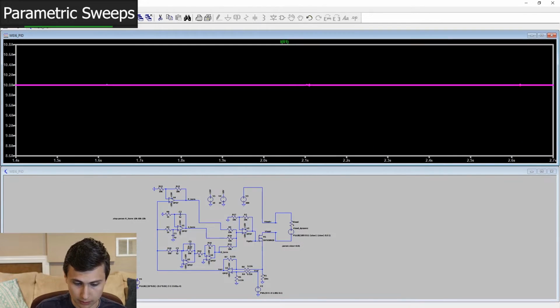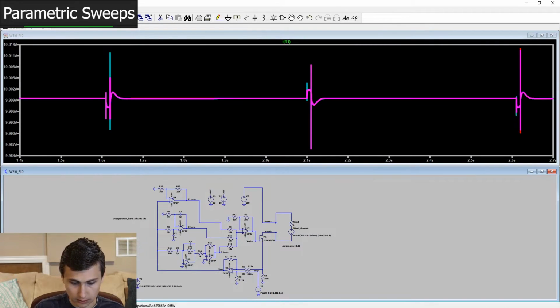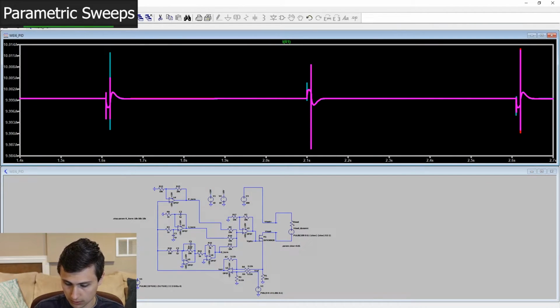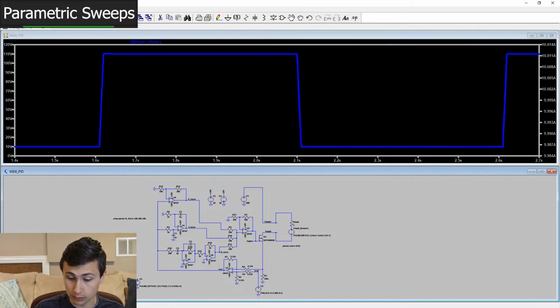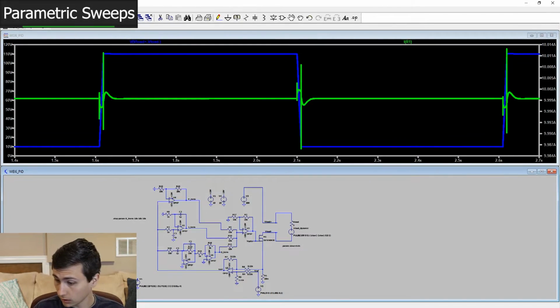And we notice there are some little hiccups in the current when the load has one of those transient events. However, the current is quite constant. It never really gets much further away. I mean, it goes from 10 to 10.011. So even in a very drastic, that's like a 100 volt transient on the output. So that would be, if our controller did nothing, the difference in current through that 1 ohm resistor would be 100 amps. And our controller was able to keep that within 0.011. So we've got pretty snappy transient response.